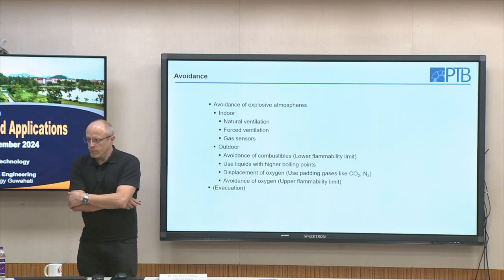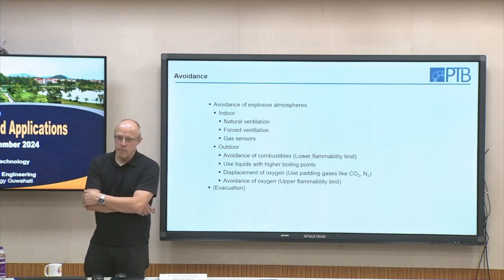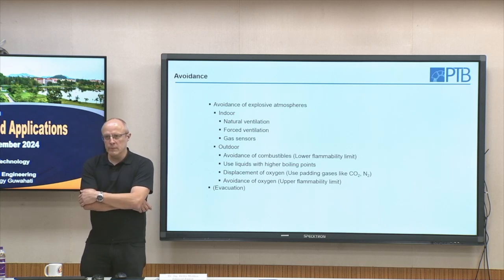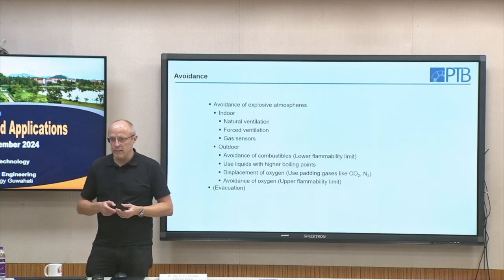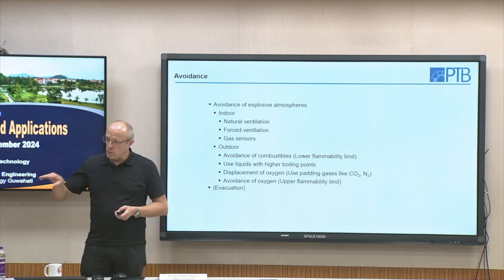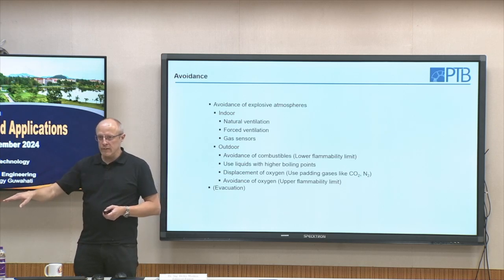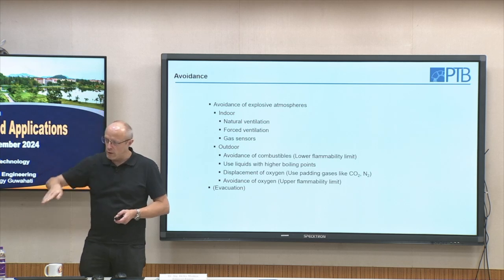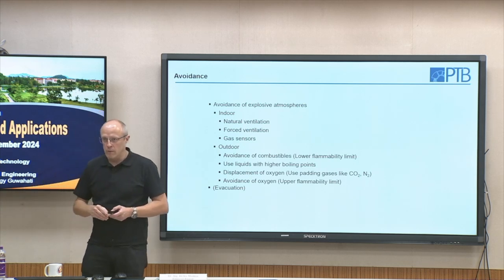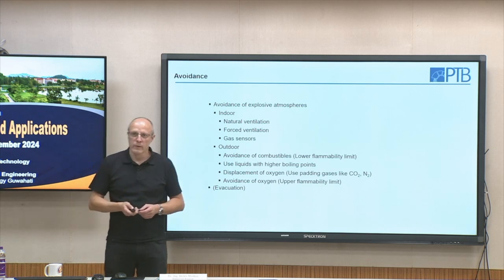Yeah, so in Germany, when we deal with combustible gases, it's mandatory to have gas sensors. So we normally have one for the heavy gases, and when we deal with hydrogen, methane, one for the lighter gases. So one near the ground and one near the top of the building.